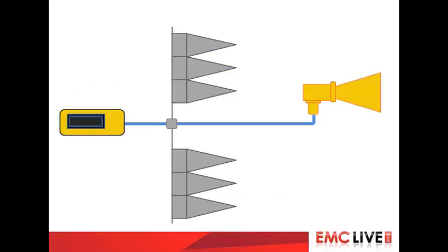And this more schematic-y sort of drawn picture shows you'll need the block on the left-hand side is supposed to represent an amplifier. On the right, there's the antenna we've been using all the time. The antenna's inside the chamber, as shown by the pyramidal absorbers there. And the cable goes via a bulkhead and in the chamber. And I think reasonable numbers would be 3 meters from the amplifier to the bulkhead, and another 5 meters from the bulkhead to the antenna, which will be on the tripod.